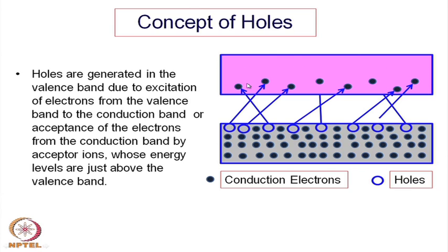In any case, these are electronic charge carriers. So our attention will be on this. When we are talking about charge carriers here, although electrons are also moving in this, our attention will not be on the electrons, it will be on the holes. So, we will say the holes are the charge carriers here. Positively charged holes, or the vacancies of the electrons, are the charge carriers, rather than saying that the electrons are charge carriers here. So, in the valency band, the holes will be the charge carriers, with the positive charge, and here in the conduction band it is the electrons which will be the charge carriers with the negative charge. So, that is the concept of a hole.